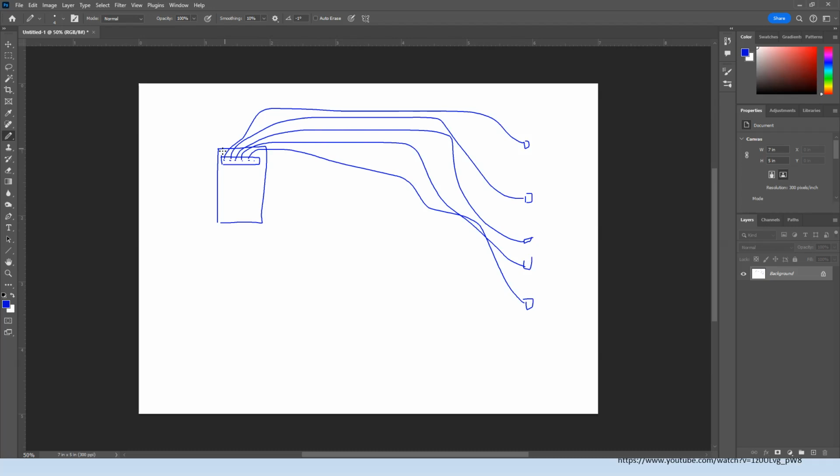It's a dry connection, just what we're doing during this lab. We're connecting a straight link between two data jacks. That's the connection between the field or desktop location, the destination location, and the patch panel, just a dry link. Here's a jack and here's a jack. To that jack, there's going to be a PC connected through a patch cord.